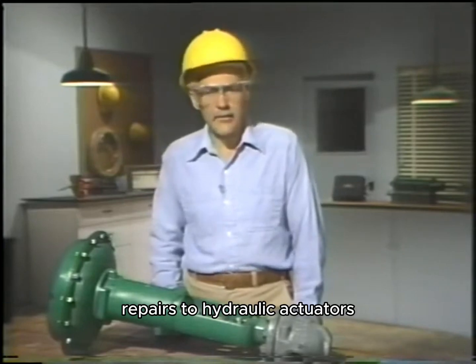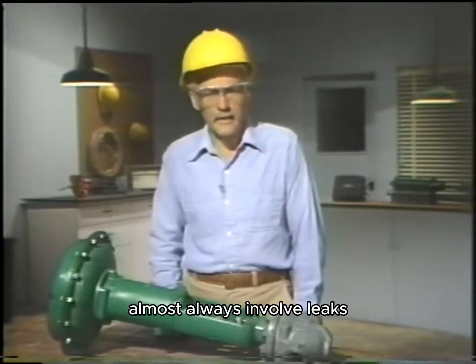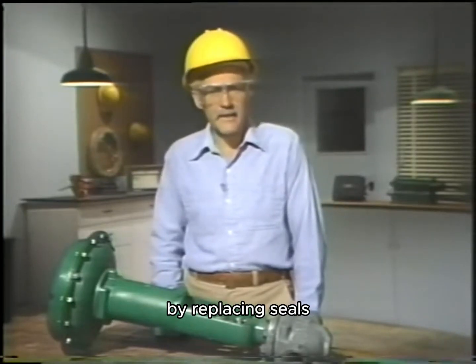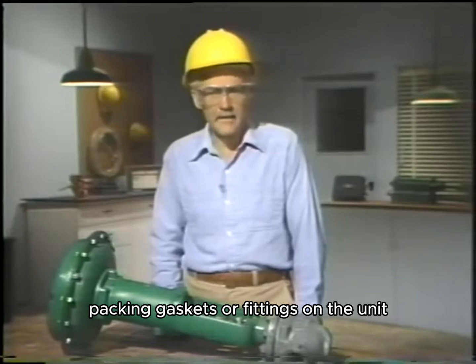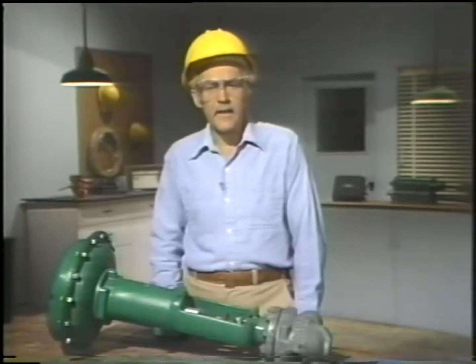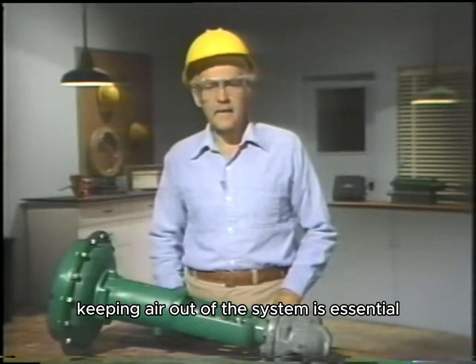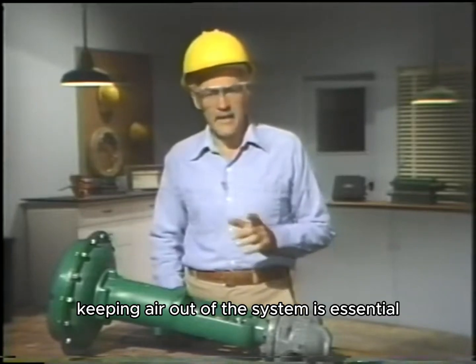Repairs to hydraulic actuators almost always involve leaks, fluid leaks or air leaks. These types of problems are usually remedied by replacing seals, packing, gaskets, or fittings on the unit. Whenever any maintenance is performed on hydraulic equipment, though, keeping air out of the system is essential.